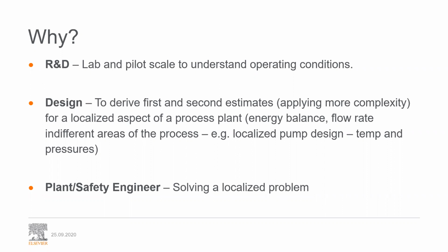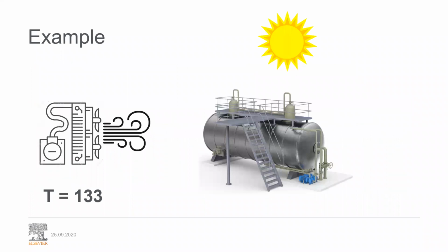So with that said, I created a bit of an example here where we can use the steam calculator and see how it can practically solve these equations. I was thinking about a tank that lives outside, and there's water inside at 3 atmospheres. So what is the temperature? The water inside would be liquid until the temperature reaches a certain value. And before that value, I need to start my convective cooler here to decrease the temperature, or some cooler, just a kind of simple drawing. So here the result is that I'm going to have to turn on this convective cooler at 133 degrees. But let's look at how we would find that number right away.